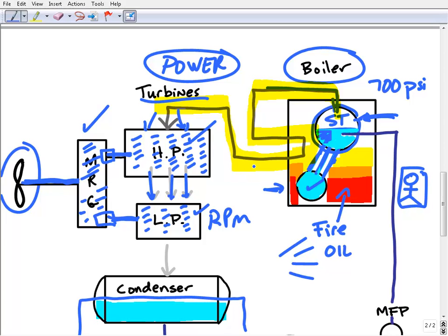The reason why I said it's really critical that we get any moisture out is that when the energy that we're going to introduce into this high pressure turbine, and both of these turbines, if by any chance you get a little water droplet here, let me just draw some water droplets like this. At the power that we're talking about, these little tiny droplets can act almost like grenades or rocks that we would throw in, and they would knock off these fan blades. That's bad. They can damage the turbine, ruin the whole thing, and even cause an explosion, because these fan blades would just get destroyed.